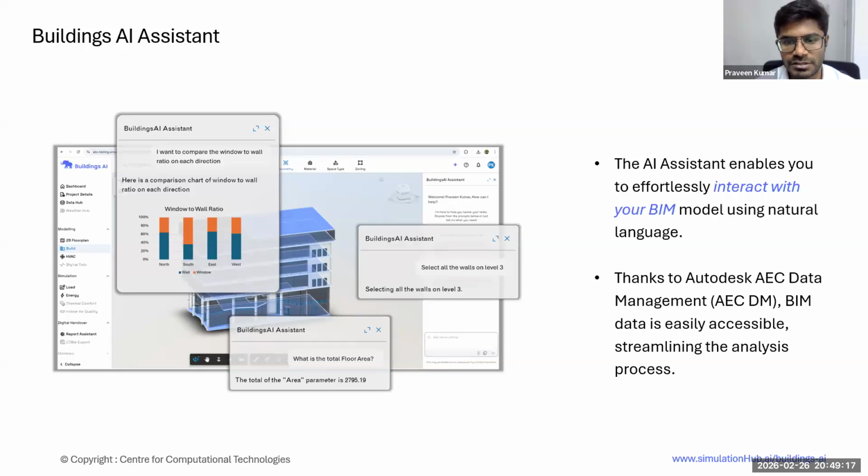There was one more question from Chris Flood. Does this tool perform the ASHRAE heat balance method? I guess that is answered. Yes, we use the EnergyPlus engine in the backend, which uses the ASHRAE heat balance method for load calculation and energy simulation.